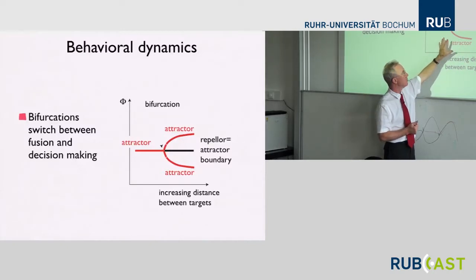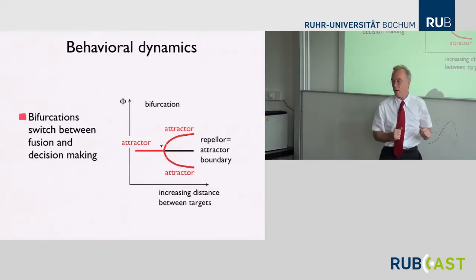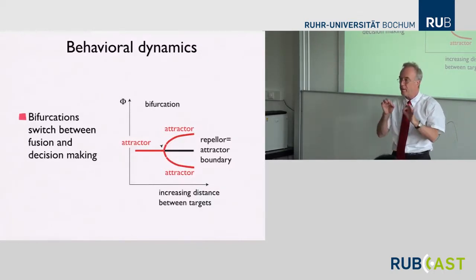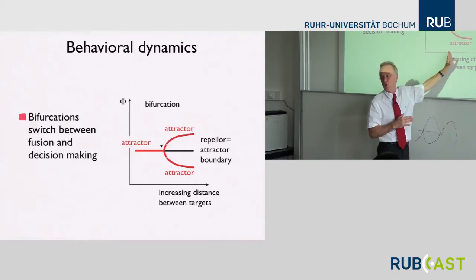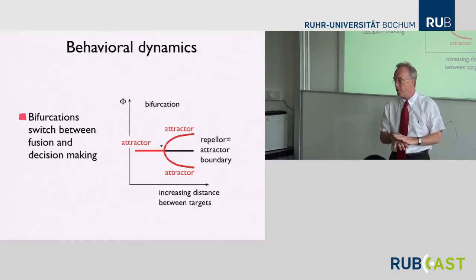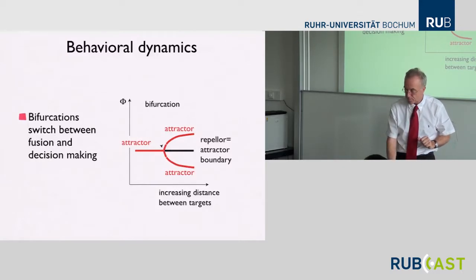And then we're trying to classify that according to these 4, and then write down the equation that has the right bifurcation. And we choose the parameters accordingly. And I'll show you this now for obstacle avoidance. It's a little bit more complex situation, where we literally tune the parameters so that the bifurcation happens at the right physical condition. And when we do that, in robot implementation, the system works reliably and satisfactorily.